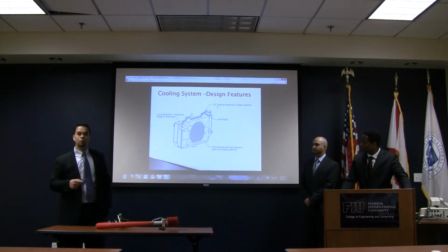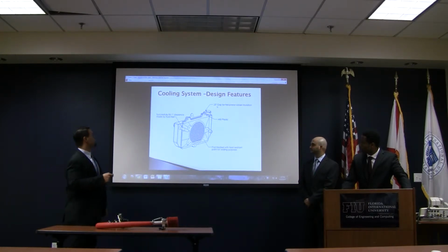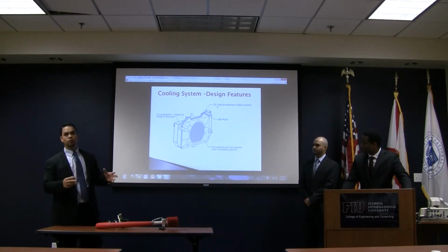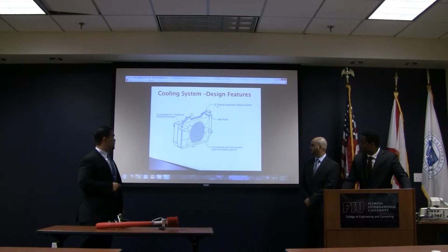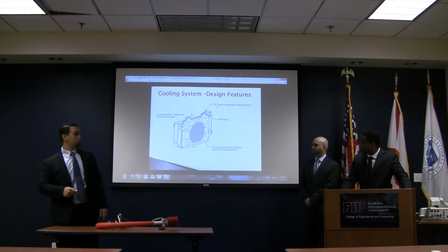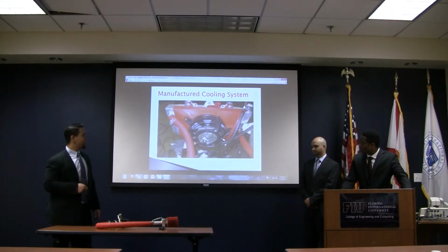We chose this radiator because it was the closest to the factory YFZ 450 radiator for the engine. We were also successful in reducing heat transfer due to conduction with neoprene rubber insulation for all 3 mounting points. And the fan shroud was then post-treated for sealing purposes of the plastic material. This is the finalized manufactured and assembled cooling system. As you can see, the neoprene on the mounting of the fan shroud, and it's successfully cleared this 1-inch gap dictated by the fluid inlet.